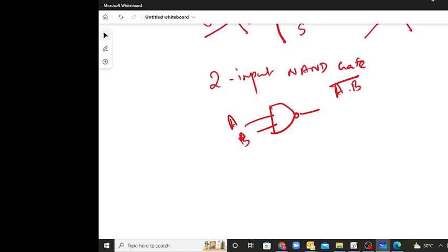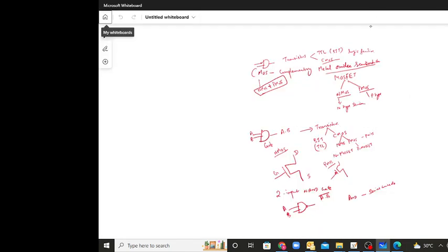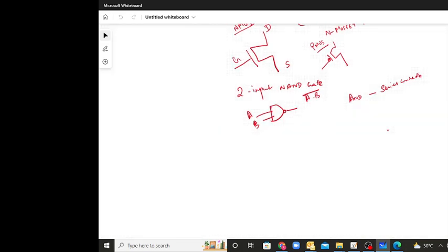If there is a whole bar in the circuit, it can be directly implemented, and every AND operation will be converted to a series connection. The OR operation will be converted to a parallel connection.